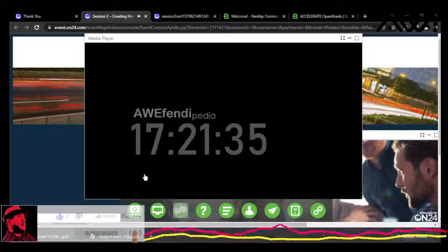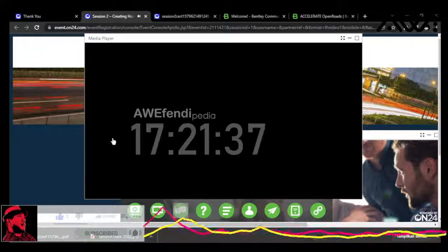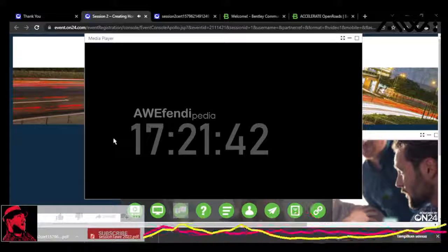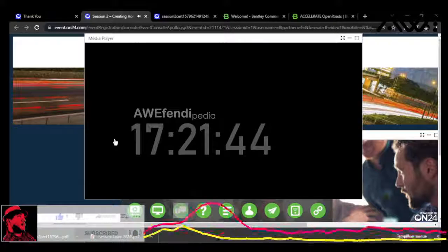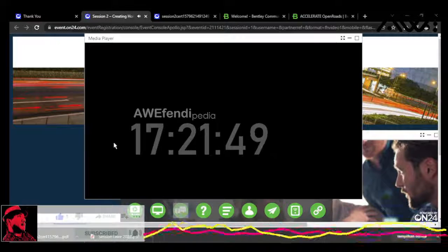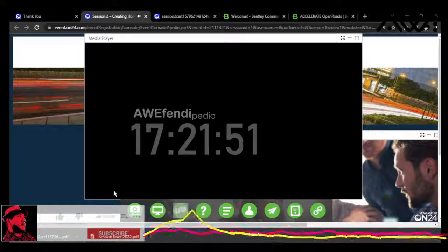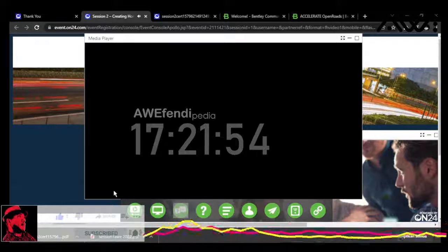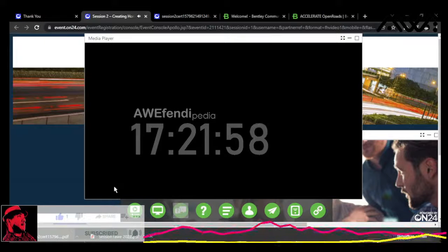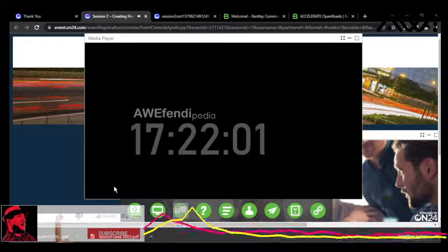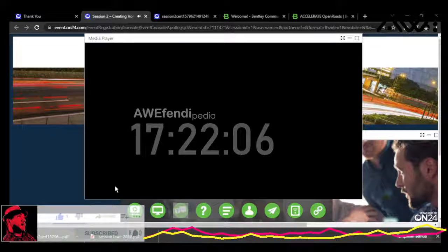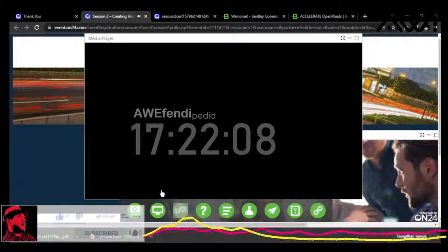The bearing is still free so that I can move that in any direction I want, but the distance is locked. Now I want to input the bearing, so I'll click the right arrow, and I get the field to input the bearing for this particular element. So we'll note it's south 89°02'28" east. So I'll show you how to key that in first of all, and then we'll move a little faster. So to key this in, I'm going to key in south 89, and I'm going to use a colon, 89:02:28.